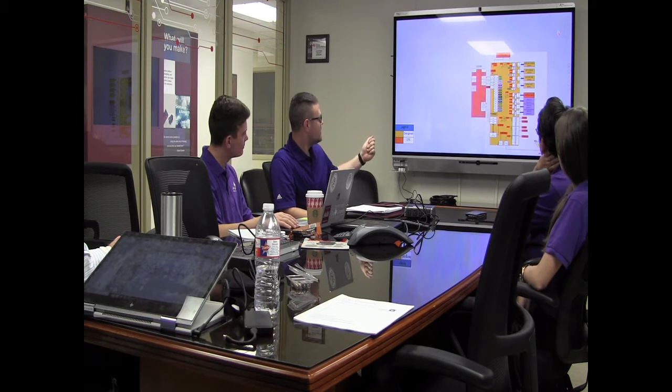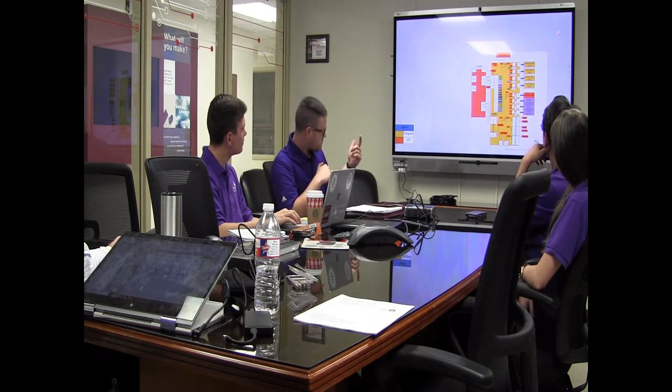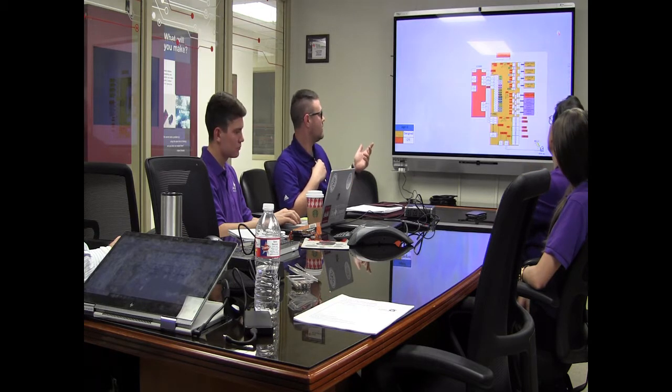Yeah, so that's that. We also have an additional 6-pin conductor that connects to our CC3200 intelligence board. It has system-on-chip Wi-Fi. We pass through the I2C line, so the data and the clock. The clock is all downstream, and then we also have a GPIO on the N/OE port, and we give it the PCA9685 5 volts from earlier. We do give the CC3200 VCC, which is 3.3 volts directly through the board, and it works really well for us.